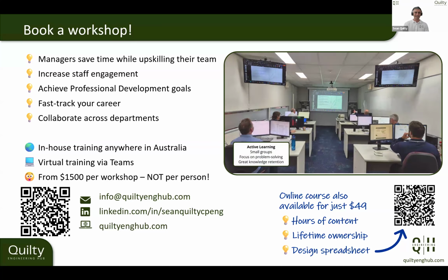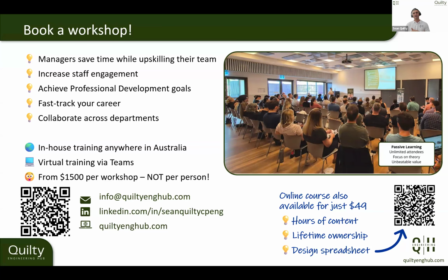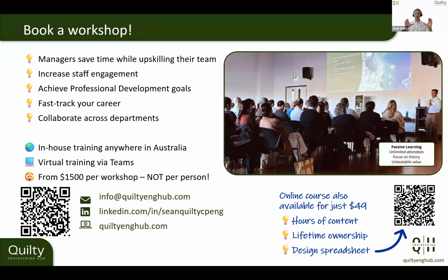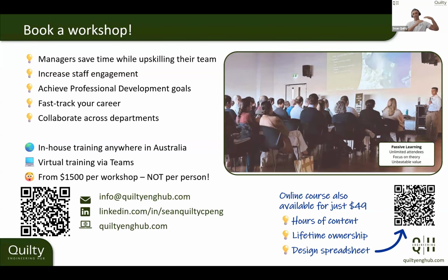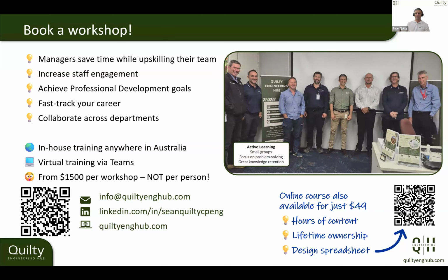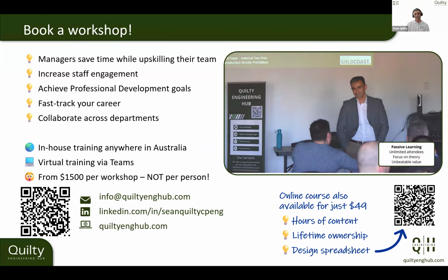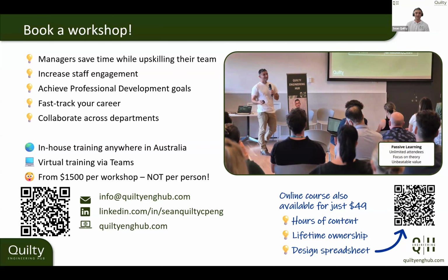Very good question. Yes, freeboard should be included in pretty much all cases. So freeboard is, if you had your cross section and the water was flowing right to the very top, there's no room for error there. And if that water was rushing through, say in a Q100 design, in a 1% storm or a 100-year storm, it's not going to be calm. You're going to have massive amounts of wind and all sorts of things going on. And so that water won't be perfectly just at the top.